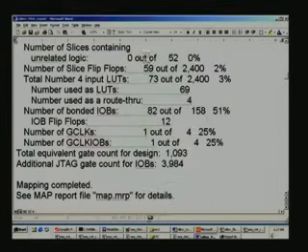We were just mentioning that the total equivalent gate count for the design is just 1093 gates, whereas some additional gates are also required for JTAG compatible IO pins, and that is about 4000 gates that you need. For a larger design this will be much larger compared to this, and we will just continue with this report.